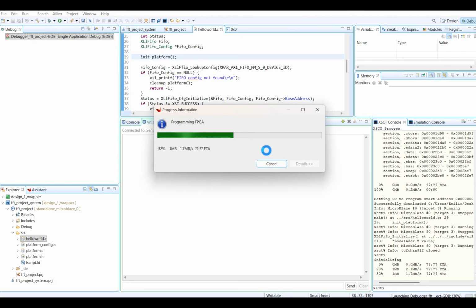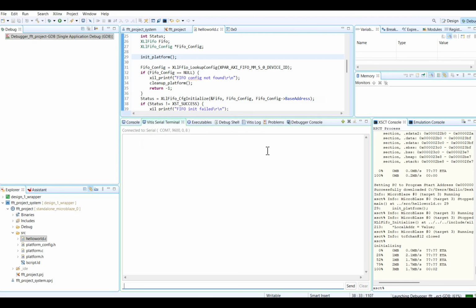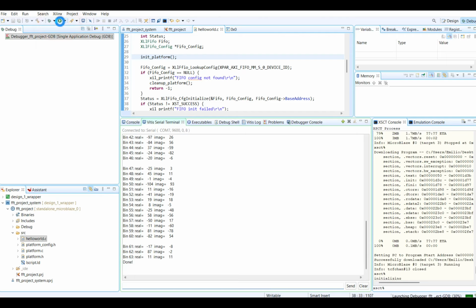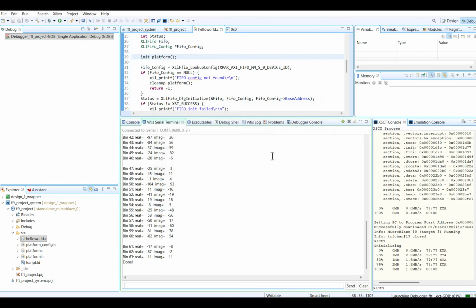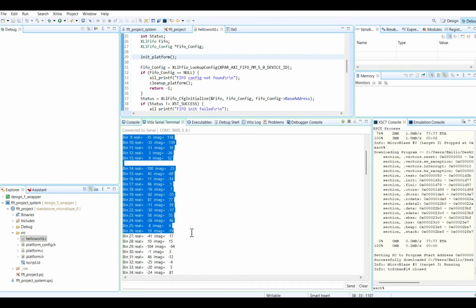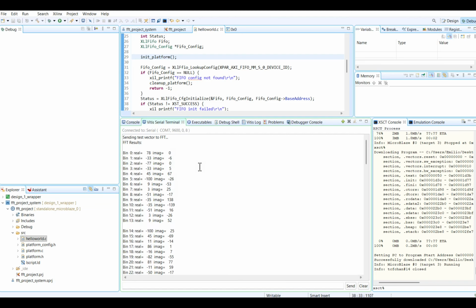Also note that the results of the fast Fourier transform must be multiplied by the 8-bit value that we calculated with the formula. So in other words, each element shown in the terminal needs to be multiplied by 85. 85 is called the scaling factor. The reason for the scaling factor is because we chose to use radix 4 in our FFT settings. This is the ideal setting to choose because although it introduces this extra step, it makes overflow impossible.